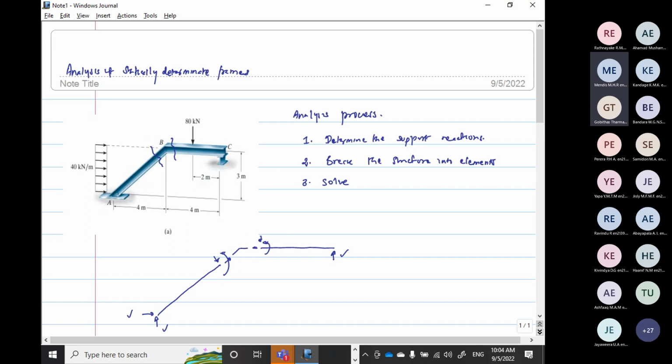So now in the rigid element, there will be equal and opposite actions to these three actions on the other side. Equal and opposite of the actions or reactions on the beam will be there on the rigid element. So the rigid element will be preserved as a rigid joint and it will be in equilibrium. Okay, so that is the approach we will be adapting.